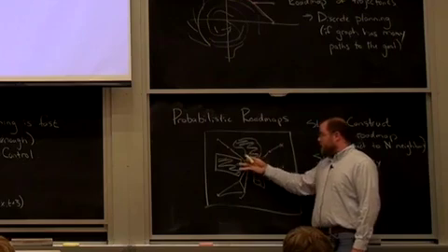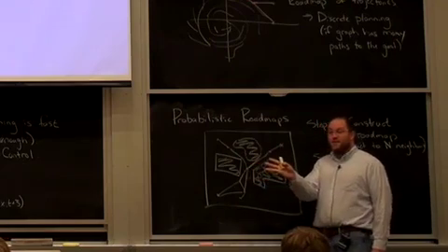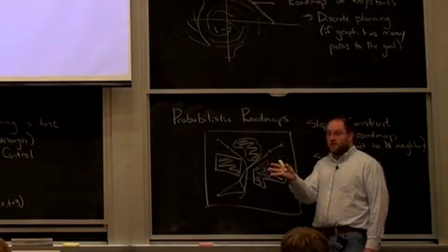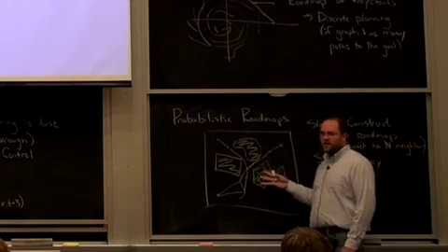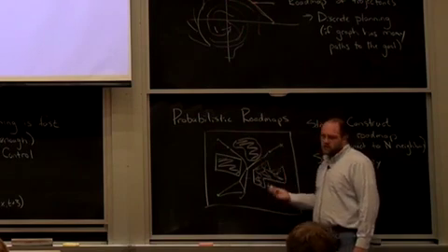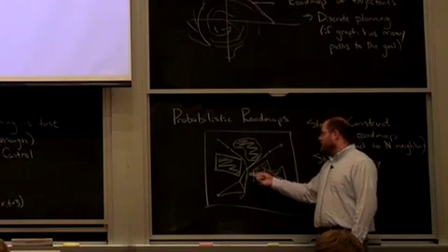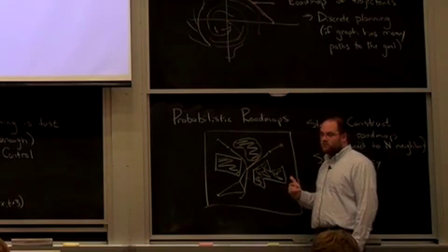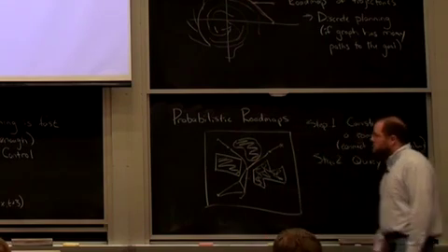And the other thing is if I have a model of how those obstacles are changing, then naively that just adds one dimension in time, let's say, to my plan, and I just have to do a higher dimensional plan. But I think the case you're thinking about is if these things are just moving on their own, I don't have any good model, I suddenly find that I'm obstructed, then again, you could dynamically replan, either taking a different path here or making a new edge if you had to. I don't think it breaks the fundamental goal.